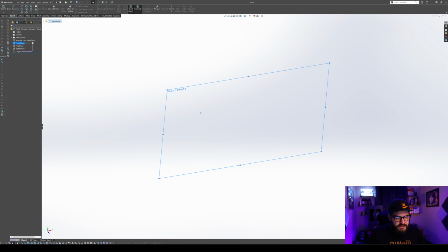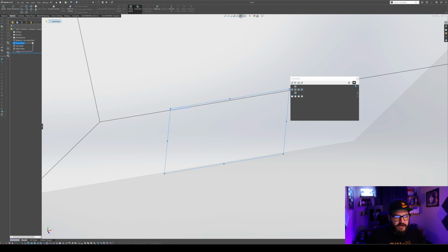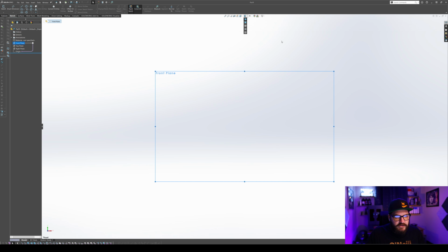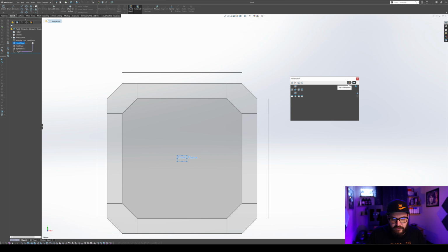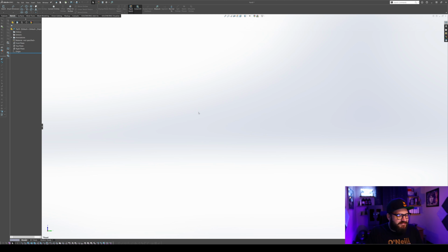But for whatever reason, SolidWorks just does not give us that option. They do give us the option, and this is step one of what we need to do: come in here into your little cube, press the space bar or this button up here, and come to your front. If I hit space bar, this little button right here lets you change it to Z-axis as up. And I was like, sweet, they finally did it. I could live with the X coming forward and it being on a different corner.